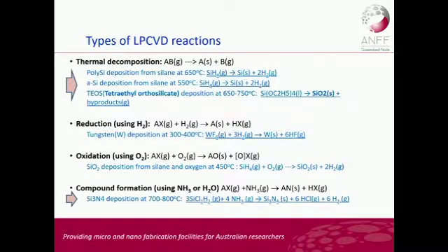And I just listed some of the LPCVD reactions. There are 4 types of reaction: thermal decomposition, reduction, oxidation, and compound formation. In semiconductors, usually these two processes are very commonly used.